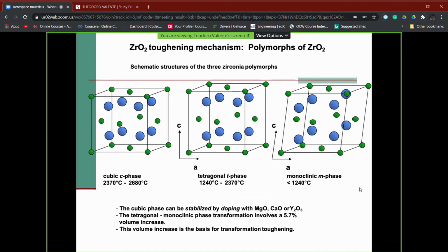And since this transformation temperature is something around 1250 Celsius, and I told you before, as an average, we can also have higher values for high-performing engines. As an average, 300 microns of thickness of zirconia is able to establish a temperature difference of around 250 Celsius, as I told you before.